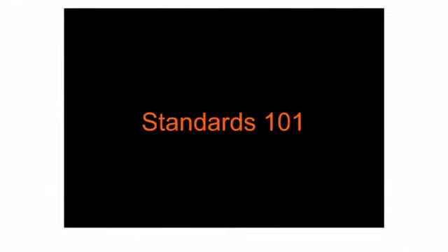And with that, I want to start the technical part of it, and I call this Standards 101. For some of you, this is probably what you already know or live by, but some others are sometimes confused between what is UL or what is IEEE, and we hear C37, and there's ANSI, and there's IEC, and this is NEMA, and so what is it, and where does it fit? And when you have equipment that has a label with a specific standard mentioned there, what does it mean from the performance point of view, or even from the legal or liability point of view in case you have a problem?